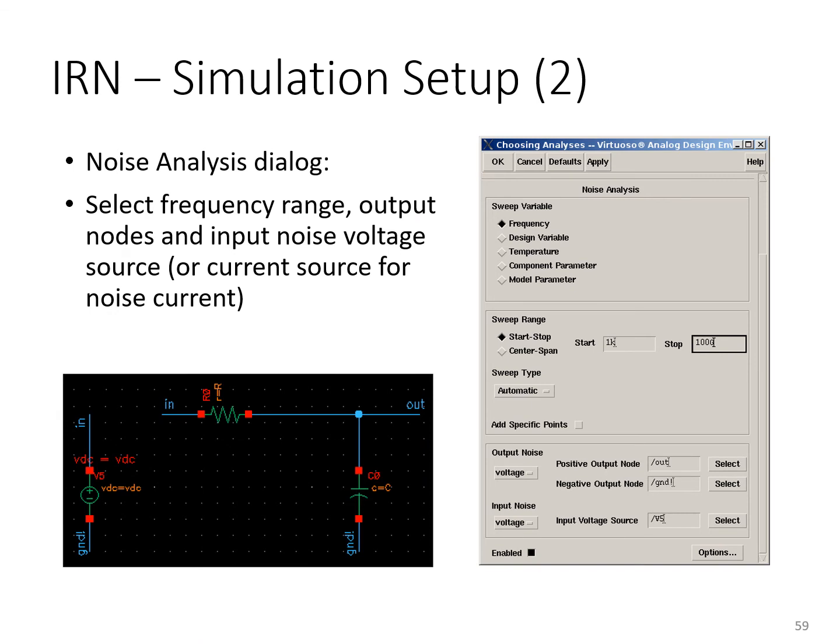And when doing noise simulations, I think it's always great to get your feet wet by starting with a really simple test circuit like this one, and you know analytically, very simply, what the result should be. It should be kT over C at the output. And in fact, there's very few non-idealities at play here. You should get almost exactly kT over C if you set up your simulation properly. So it's a good test case because you'll know once you've done the simulation if you've set things up properly and if you're doing noise simulations properly.